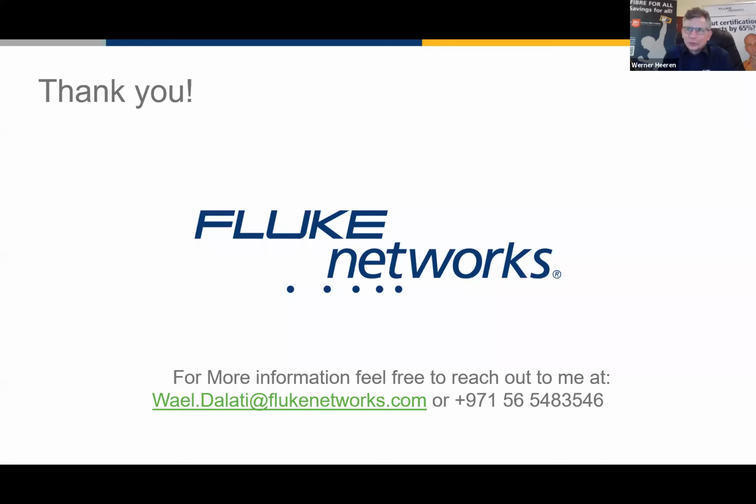There is still one question, or it was asked already similar. If a consultant asks for the reflective events on the end connector, but you have only one launch cord, is it then okay to test from both ends, but only one direction? So they're asking, is it correct or not? Since they only have one launch cord, still the consultant asks for the reflective events on the end connector.